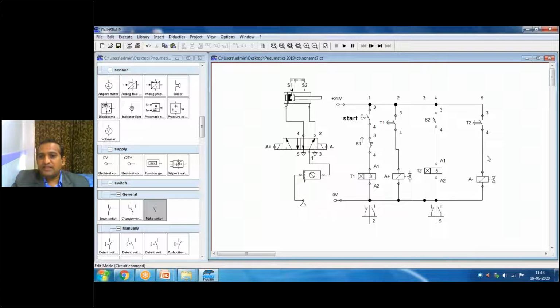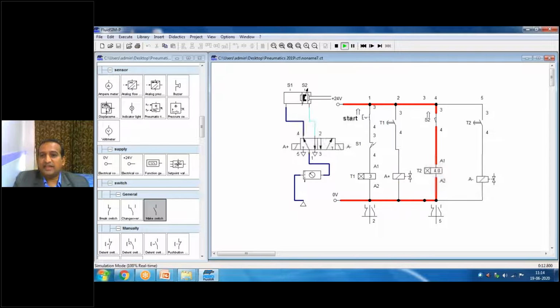So these are called non-retentive type of timers. Okay, retentive types of timers are there. I'll discuss later. So here you see how beautifully this circuit is working. Okay, start. It is the master key, main button. It is in your hand. So there is a delay. First is a 3 second delay, and here there is a 4 second delay.